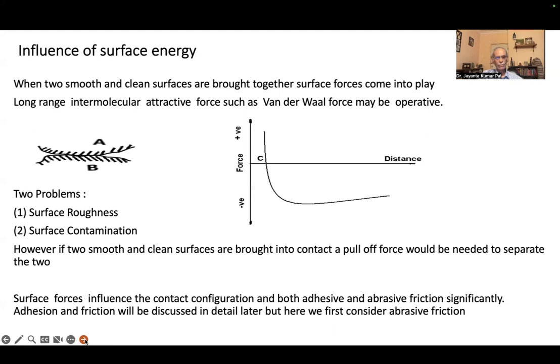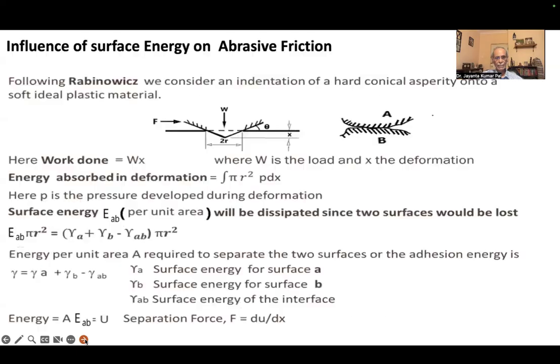Surface forces or the surface molecular forces influence the surface configuration. And both in adhesive and abrasive friction, this will have a great significance. Because if the contact area is increased or decreased due to the extramolecular forces, the frictional force or the coefficient of friction will be different. Again, we'll go into the detail later on. For the time being, let us look at the influence of surface energy on abrasive friction.